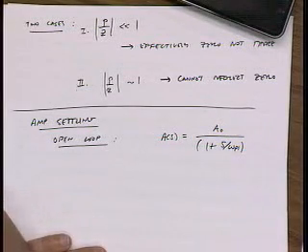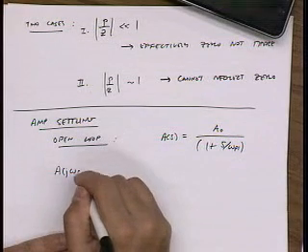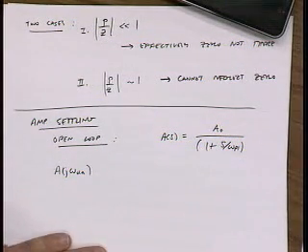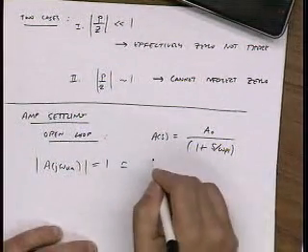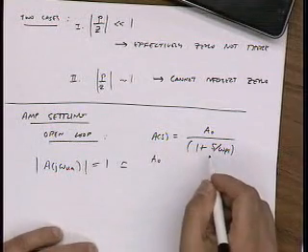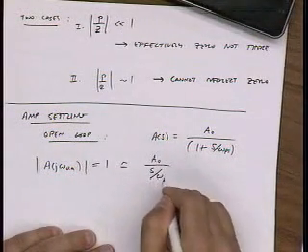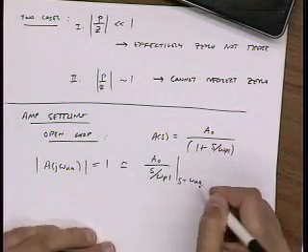Okay. Now we all know very well that the unity gain frequency of the amplifier, let's call that omega UA, is simply given by, so I'm going to assume that close to unity gain, this term dominates, so this will become S over omega P1, where S is equal to omega UA.